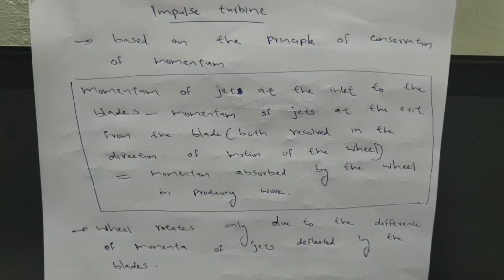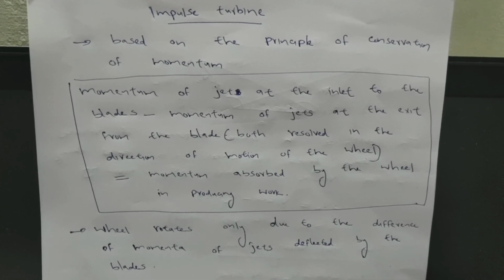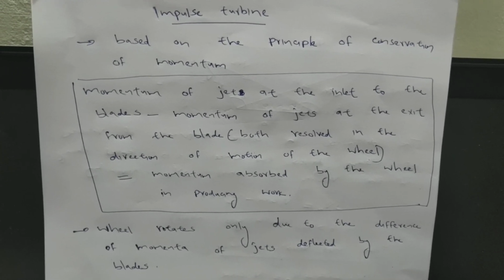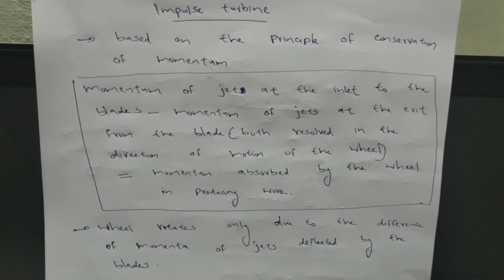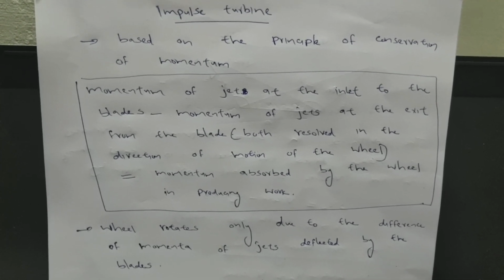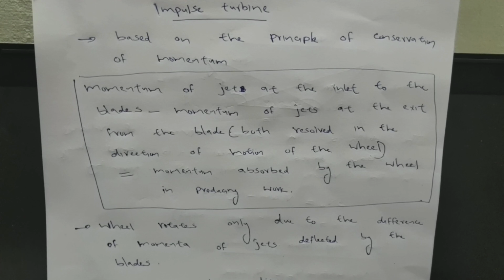So remember, once the steam has passed through the steam nozzle, then there won't be any change in its enthalpy, because the entire enthalpy change takes place in the steam nozzle. After that it is just about velocity, and there won't be any more pressure drop.